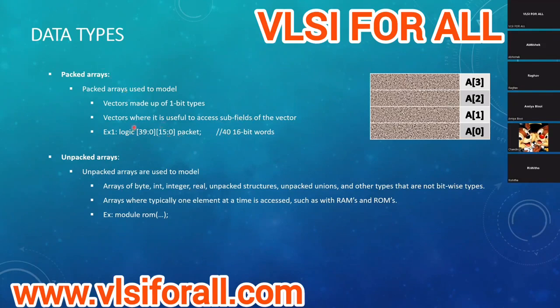Then unpacked arrays are used to model an array of different data types, like an array of bytes, integers, reals, unpacked structures, unions, an array of anything. It's for arrays where you typically want to access one element at a time. So there you will use an unpacked array.